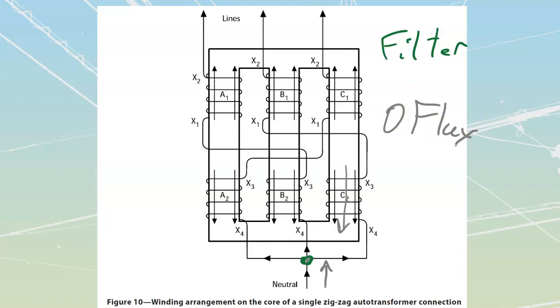It's going to take the neutral current, equally divide it up, and ultimately send that current out to the lines in a balanced manner. No matter what size this neutral current is, or what phase angle that neutral current comes in on, it is going to split it up. So if I had 17 amps, it would split that 17 amps up equally and put it out onto each of my lines equally, which is what keeps my entire system in balance.